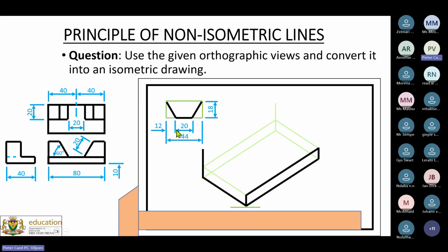The dimensions that you have to have here are not to say that it will be perfectly dimensioned. You can draw it freehand by hand, because this is actually a type B line type drawing somewhere on your paper. Don't rub out this part, or don't let the learners rub it out. Why not? Because the examiner is saying, where did you get the proof from to get this drawing? So therefore he wants the evidence on this part over here.